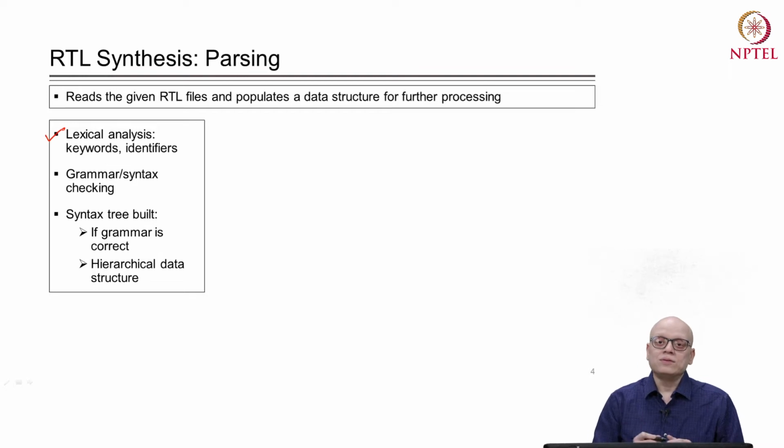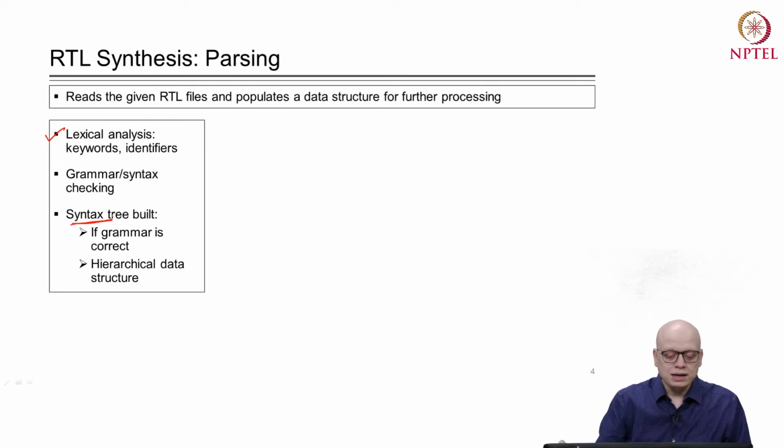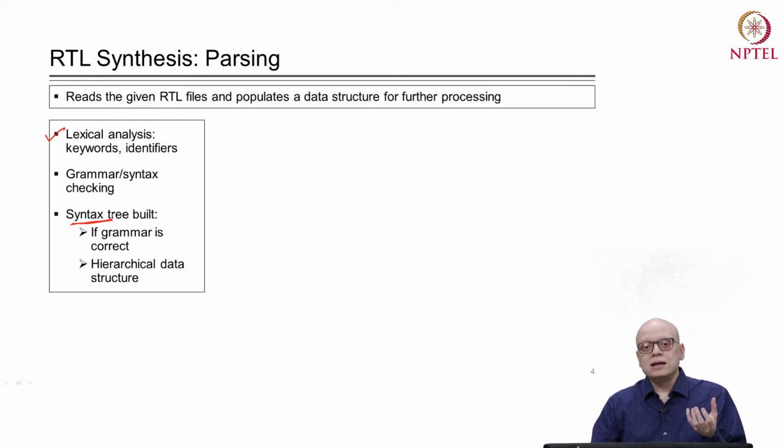But if the given RTL code is syntax error free, meaning that it follows the grammar correctly, then the tool will build a data structure, typically a syntax tree or a parse tree, which is a hierarchical data structure. By hierarchical we mean that if some RTL construct contains some other RTL construct, the parent-child relationship is maintained, and based on that relationship a hierarchical data structure is built for the given Verilog code.